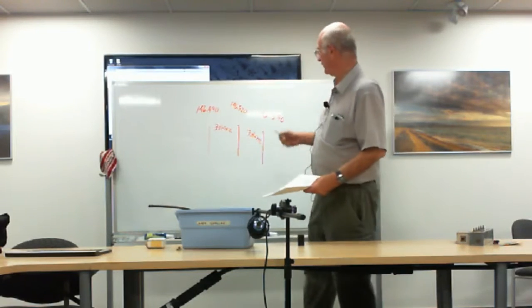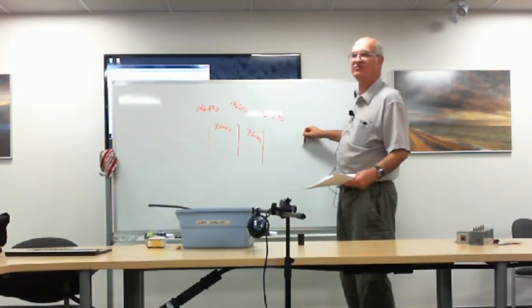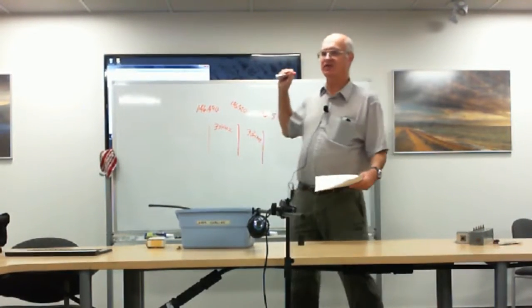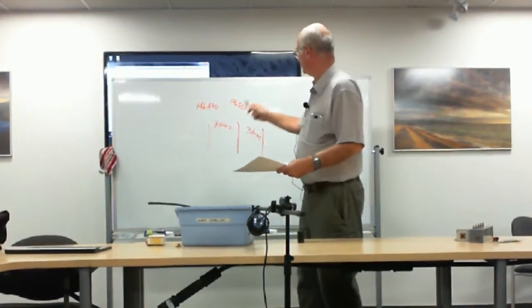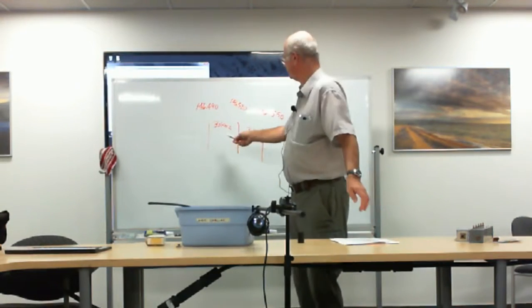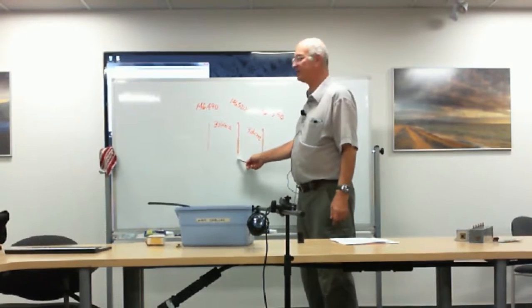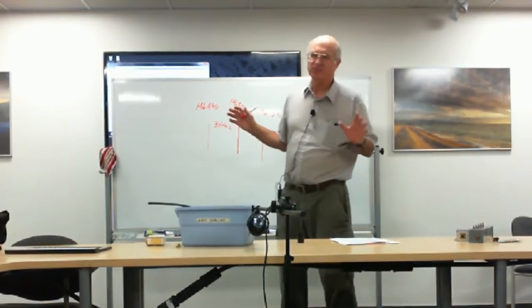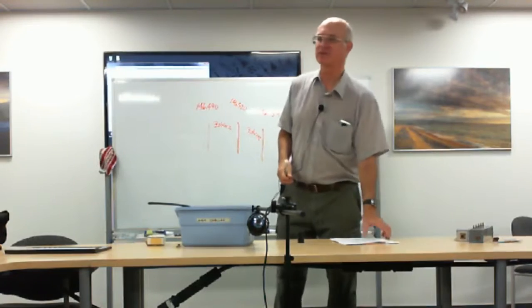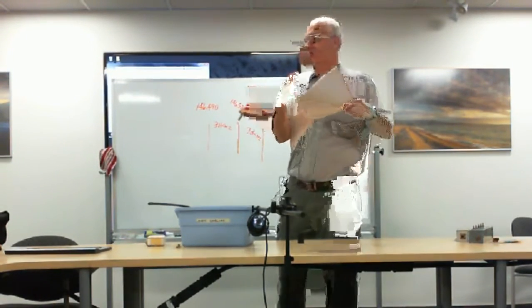If you get two frequencies, you mix them together, if a product is created that ends up on a frequency someone else is using, you're going to get it. Now this is a local effect. This will only affect the receiver within a few kilometers typically. So if somebody's on this frequency on the east end, and this guy's 2 blocks from you, and you're here, it may not happen. Because one of them won't be strong enough to be captured in your receiver and get past your bandpass filter.